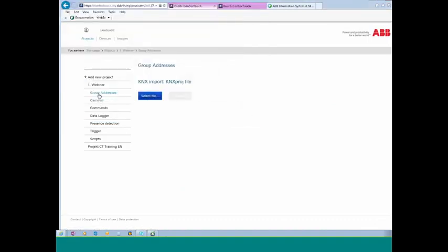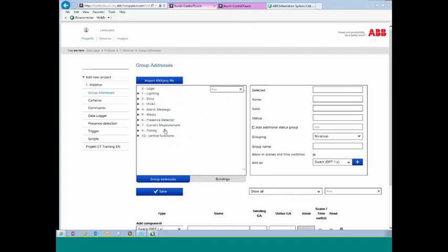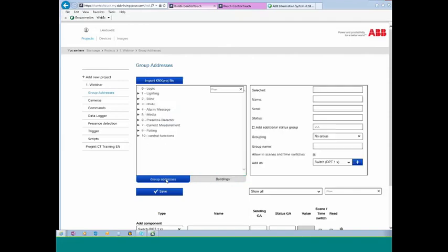If you did this once, just to show you, you will get the complete group structure and from ETS also the complete building structure. That means what you see here are all the group addresses and the physical addresses of the components, but not the components, the KNX devices itself. And then step by step, you can rebuild your own visualization structure.